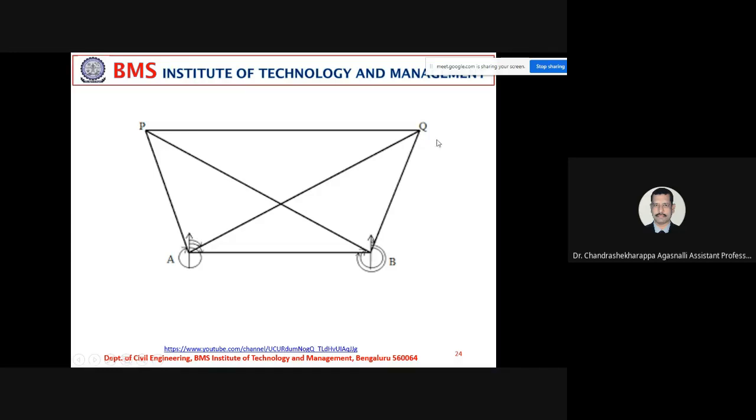So what is the angle here? You can check it. This is your north and it's 0. When you fix the compass here and you want to mark this point, what is the angle from this point? It's I think 5 degrees or 8 degrees from the north. So mark it and measure the horizontal distance using the tape or maybe the chain. That is up to you. Okay, this is one mark.